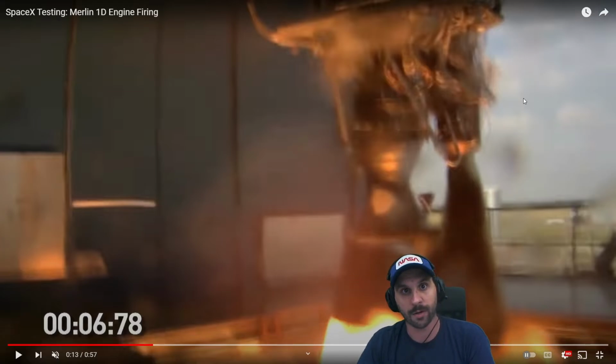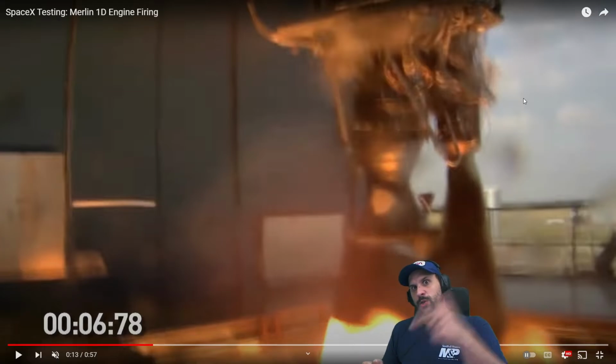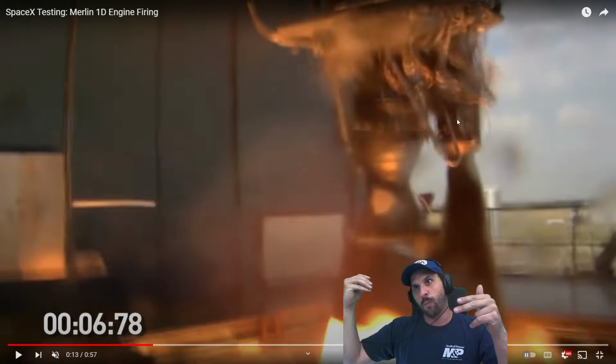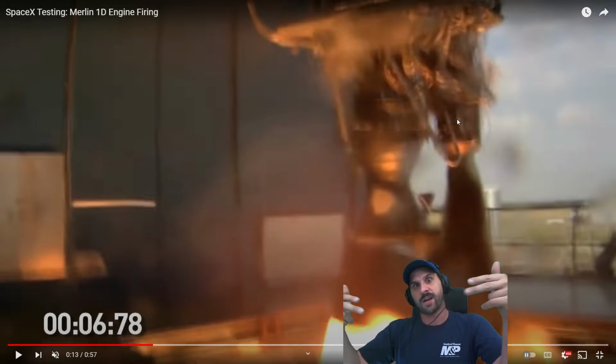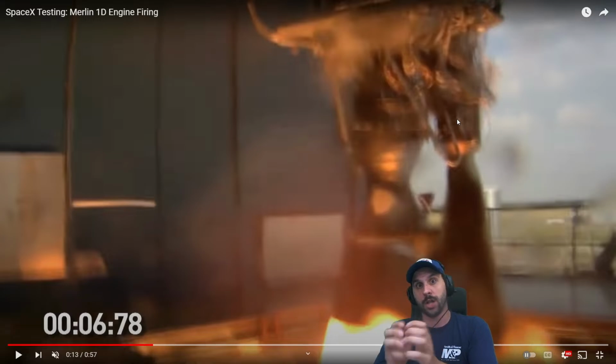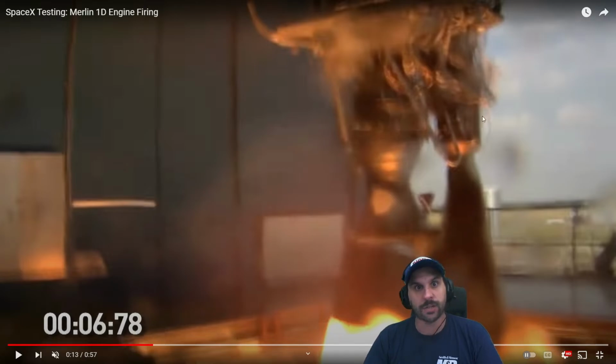most amount of power. That way, if you spray a lot of fuel into that turbine, the turbine's right here, you spray a lot of fuel and about half of the amount of liquid oxidizer in there, all of the oxygen is going to combine with all of the fuel, and all of the fuel that did combine with liquid oxygen is going to combust. That does leave excess fuel byproduct. The turbine is running very, very fuel rich.